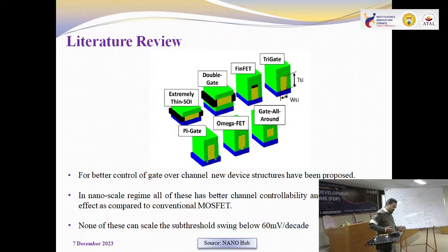So we are going towards miniaturization. Yes. But in that process, what is happening? The short channel effects are rising. So somehow we have to develop a mechanism to reduce the short channel effects. These are the architectures through which we can reduce the short channel effects.